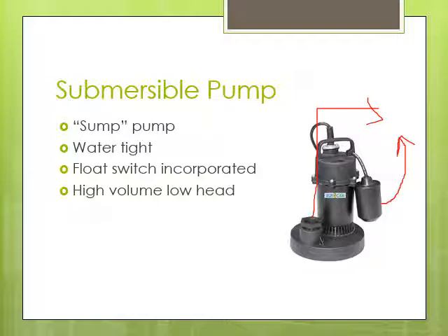Let's say it's in the middle of July, it's hot and dry. You may want to check that your sump pump isn't actually still running dry because first of all, it'll break it or wear it out. It might start a fire, or if nothing else, you're wasting quite a bit of electricity for it to spin for no reason. So keep an eye out for that.